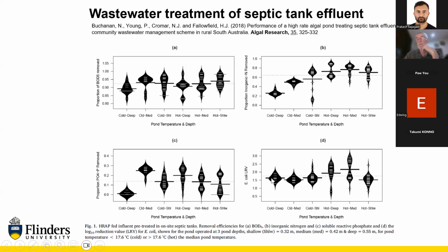And that was an interesting result because we think that with the shallow depth and the biomass that we were operating at, there was probably, even in the cooler months when you have less sunlight, shorter day length, still enough UV to affect disinfection at the residence times being applied.